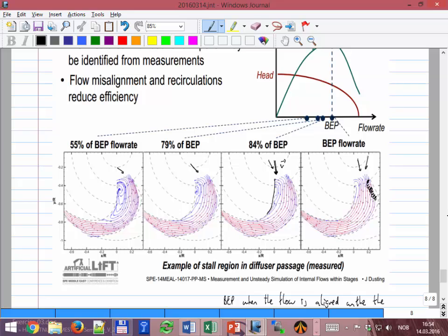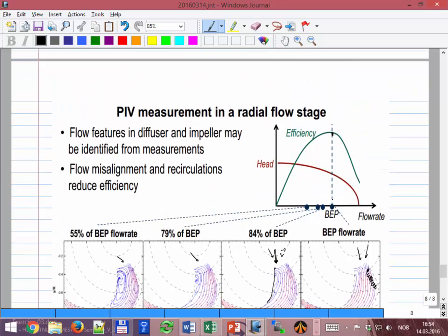Now if I increase it to the extreme, what I will see is a lot of vibrations and a lot of heating, and that causes negative performance of the pump. So to be on the safe side, people say, please don't take it beyond this rate or below this rate, because in between these two I can guarantee you a high enough efficiency, between 50 and 70%.